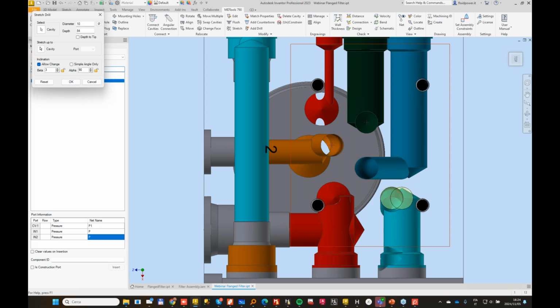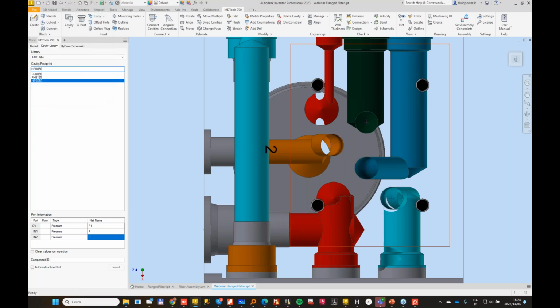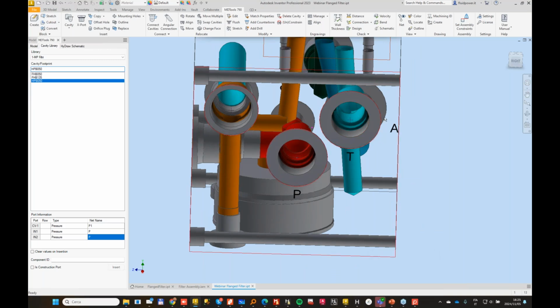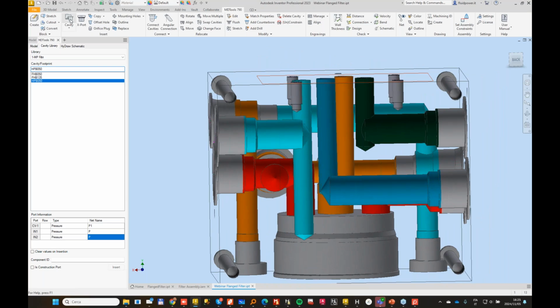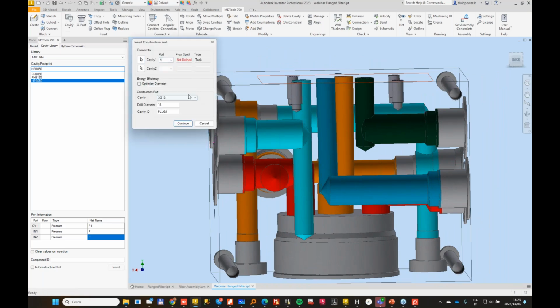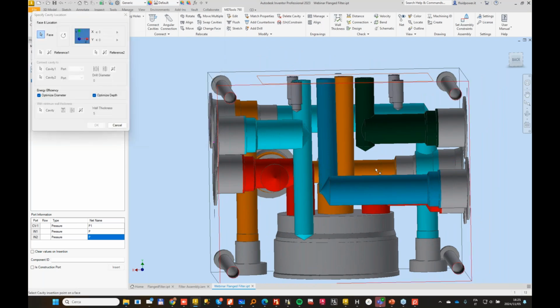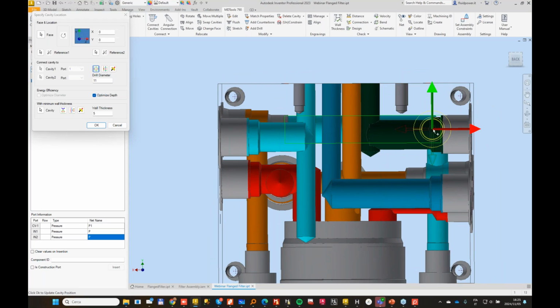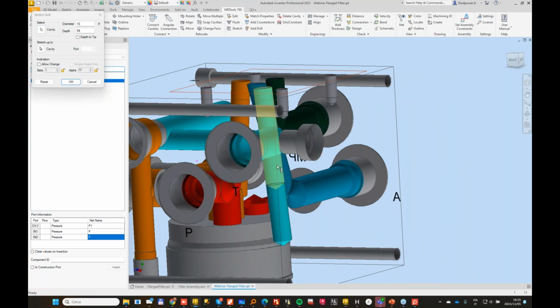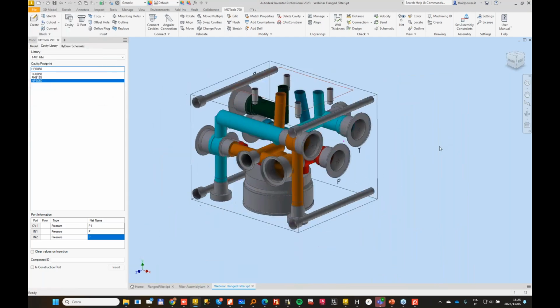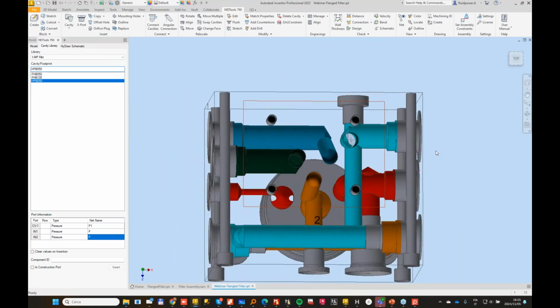So in this case, I will use 90 degrees, maybe 5 degrees is better, so that I can also move my drill slightly to the right. Also, I add a construction port to connect my tank lines. And my position is this. And let me stretch it. So the block looks almost okay.